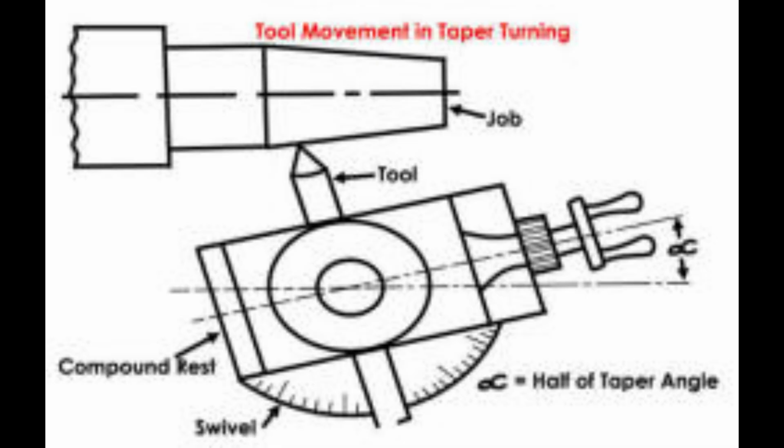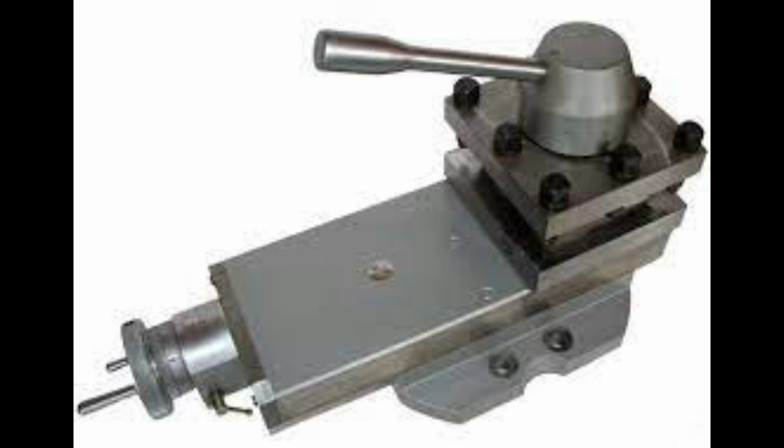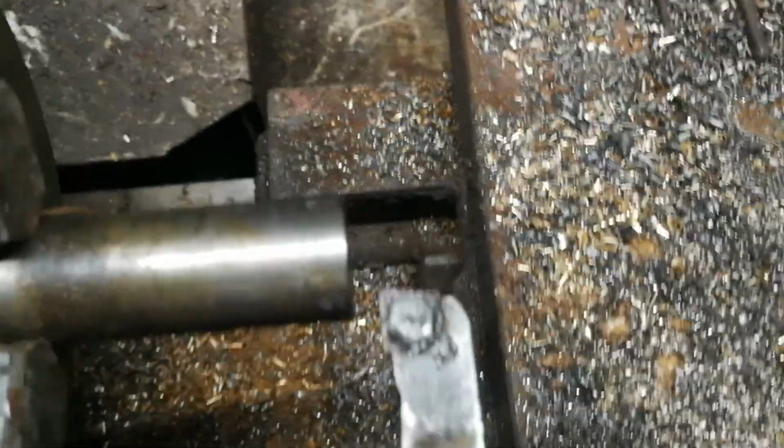When a taper is needed, and no taper turning attachment is available, the compound slide should be set to the desired angle of the taper, i.e. 15 degrees, and the feed controlled by hand. It is recommended that this is returned to 0 degrees after taper turning is completed so accurate cuts can be made for facing off.